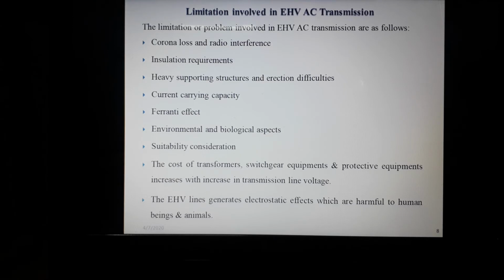Ferranti effect is the effect which shows that the receiving end voltage is greater than the sending end voltage at light load condition due to the shunt capacitance of the transmission line, and Ferranti effect may be much more severe in case of EHV AC transmission in case of light load condition.